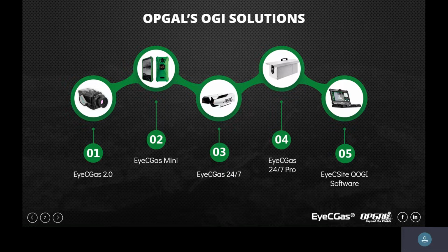And it's very important that this camera has a suitable filter for its application. If we're going to do methane, we may go with a standard filter. If we want to do it in a refinery, where methane is less important, we will use another filter.